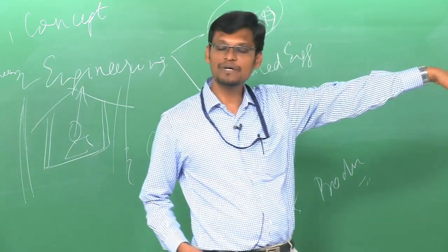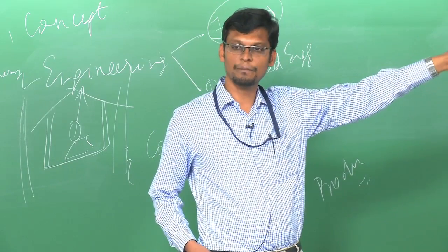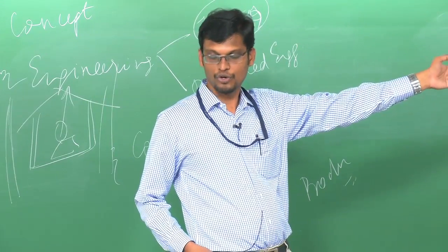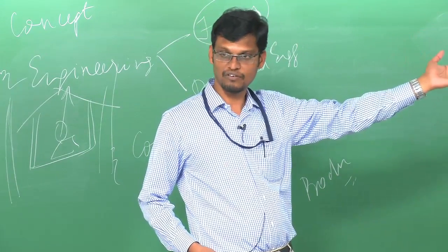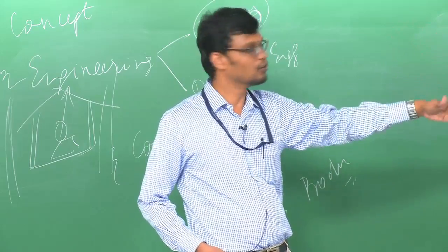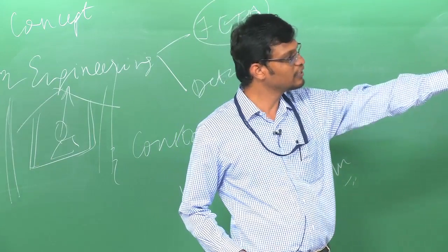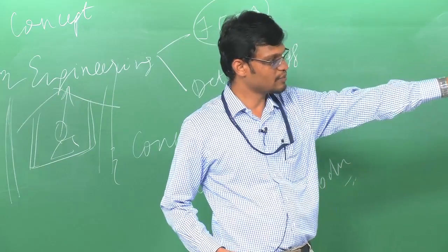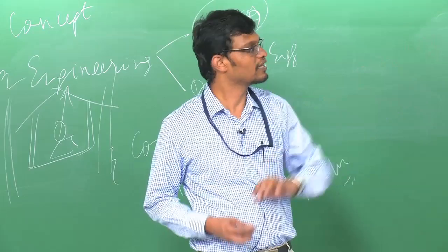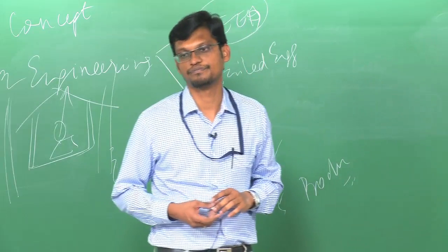And this is what happens where you have a set of guide words and deviations. Guide words are applied to parameters like pressure. So what happens when you have high pressure, what happens when you have low pressure, flow, more flow, less flow. Each of those is combined, and then you have the cause, the consequence, and the risk ranking which I told you about, what is the effective safeguard, and what is the recommendation.